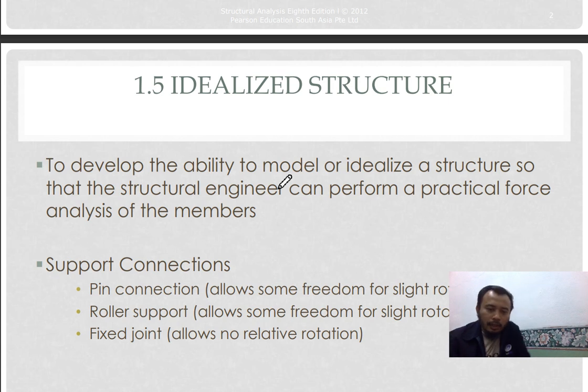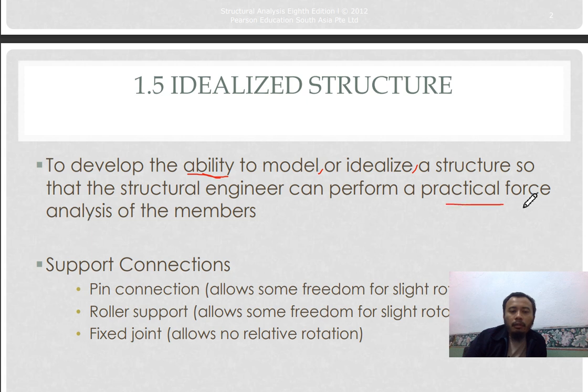This first subtopic is the idealized structure. The idealized structure is to develop the ability and technique to model or idealize a structure so that the structural engineer can perform a practical force analysis on the members. So basically, when you have a real structure you want to build, you want to model or idealize it so that it will be easier and more practical to analyze.